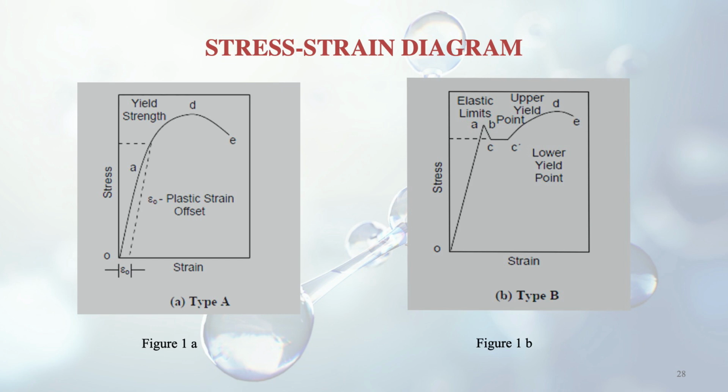And what is elasticity? Elasticity means that whenever load is applied, a certain deformation is there, but if you remove that load, then the material will come back to its original position. That much happens only up to the elastic limit. Thereafter yield will happen, and that deformation will remain permanently. So this is about the yield point, where we are going into the plastic region. The first is the upper yield point, and the next one is the lower yield point when the graph has come down. It is seen only in case of certain materials.